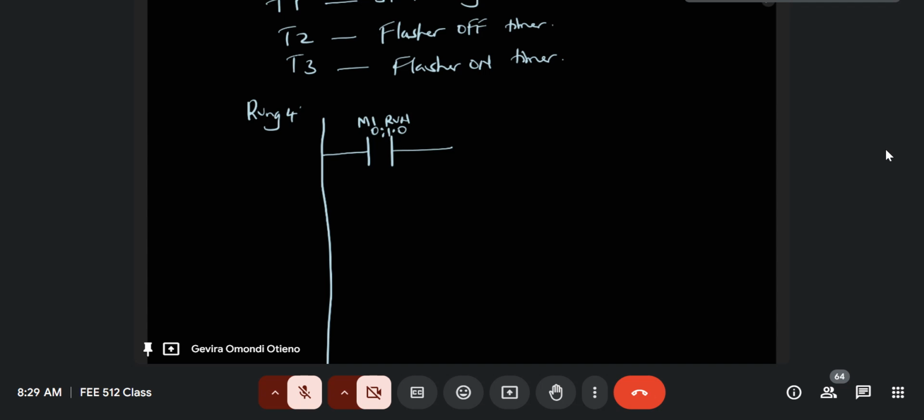Okay, it would alternate. So now, again, you don't always have all the full information when you're drawing the ladder diagram, but you try and do everything that is required in each rung. If you look at the sequence of operation and you see something is missing, you can always adjust. I don't expect that when you are designing, you already know everything to put in each rung without having to come back and readjust. So you just have to use common sense or logic in this case.